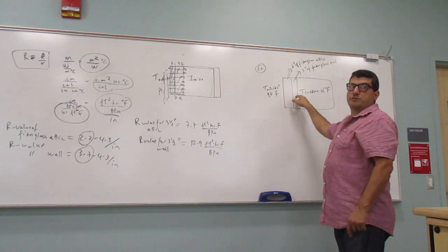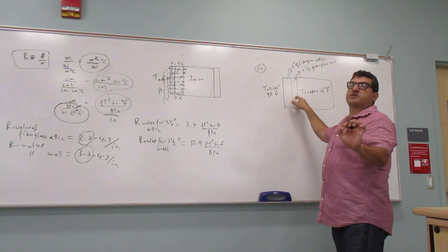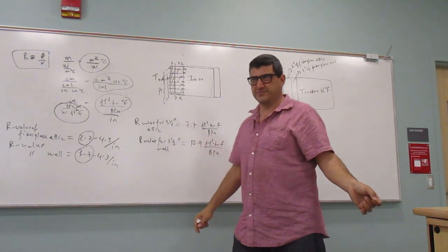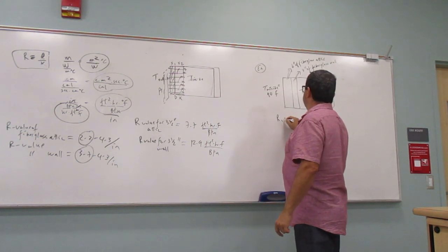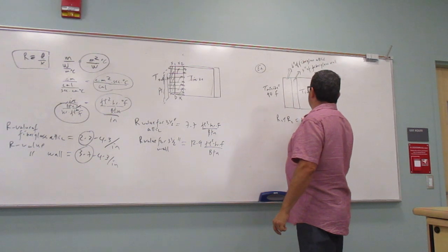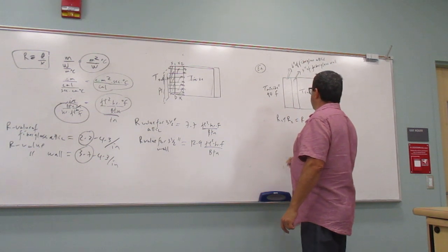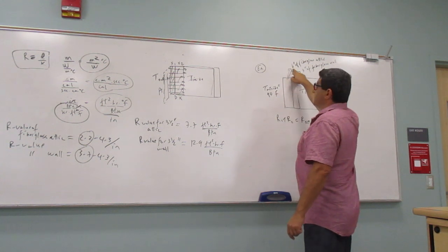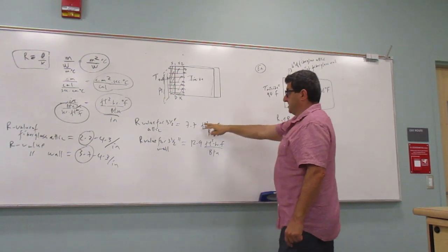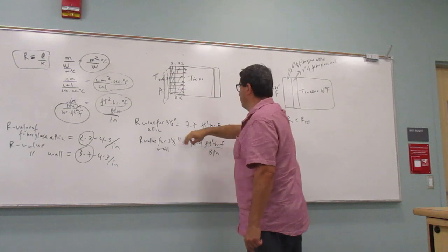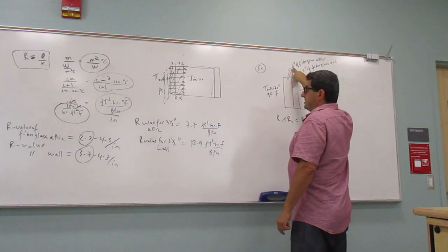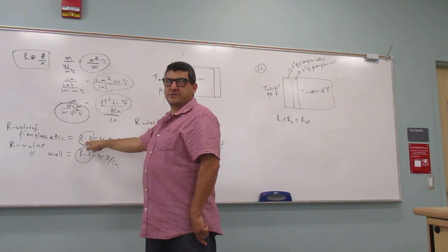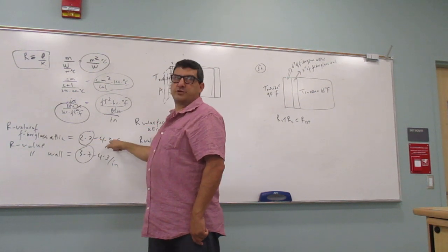So what do we know? Well, their insulation factors add up as R1 plus R2 is R total, right? So then what is R1? Since it's not 3.5 inches, what do we have to do? We have to take 6 inches, then multiply it by this guy, 2.2 to 4.3 per inch.